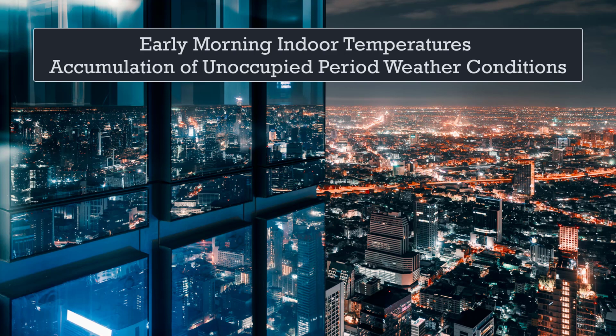So prior to optimum start, if a building's indoor zone temperature is 80 degrees, HVAC mechanical cooling is required at, let's say, 5:30 a.m. to reach desired comfort zone temperatures by occupied period begin time, regardless if outdoor air temperatures are 60 degrees or 70 degrees.